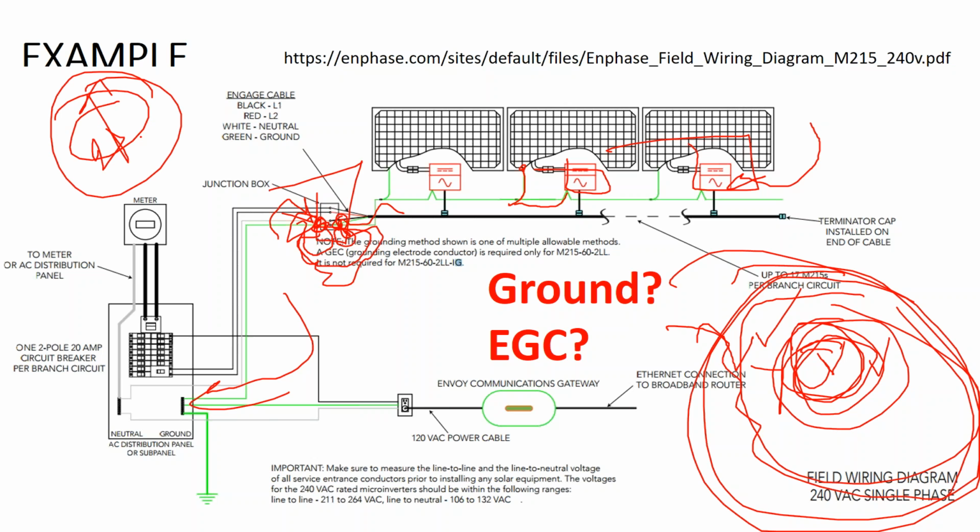What that means as a designer is a good starting point to set your conduit sizes, as you might want to look at your boxes and say, okay, well, it's designed to take 3/4-inch or 1-inch conduit. Maybe my calculations only say I need 3/4-inch, but I'm going to do 1-inch because it's just going to make all these grounding issues less complicated for my electrician in the field.